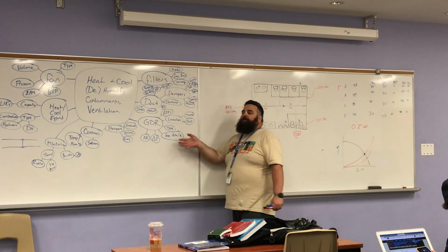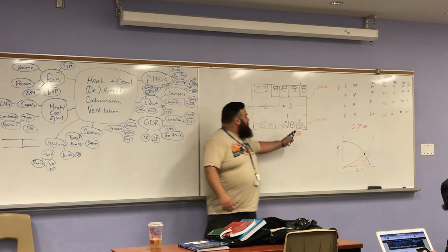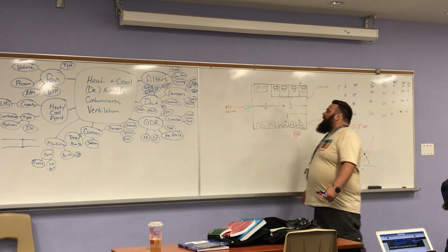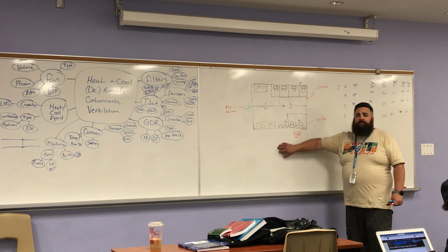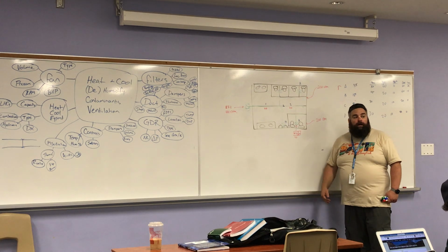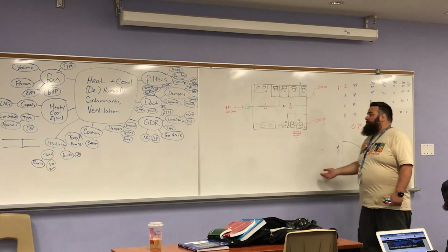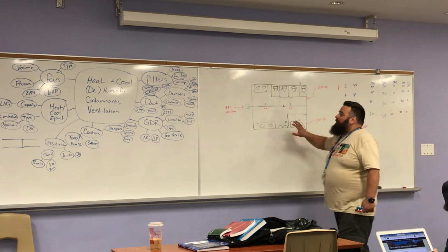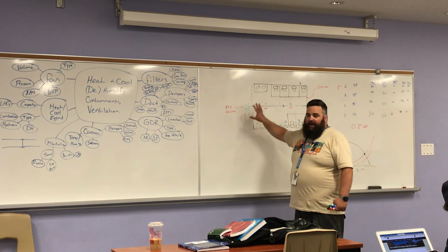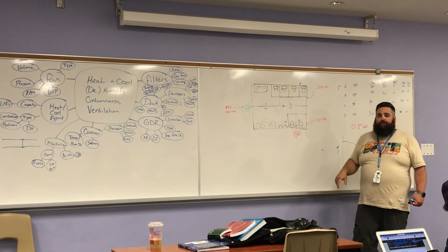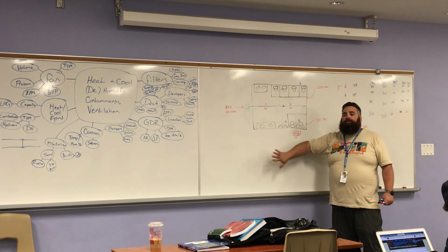It goes a little bit further. We didn't even talk about balancing dampers, which we would want to factor in. We're not concerned with filtration on this point because we're discharging to the outside, right? If I were bringing in outdoor air, now I'm concerned with filtration. We didn't talk about voltages or anything like that yet. We didn't even talk about sizing our grilles and diffusers. I wanted to introduce you to the process.